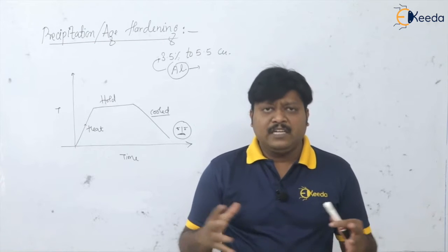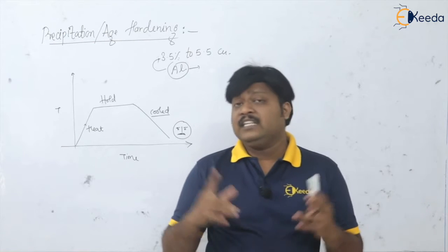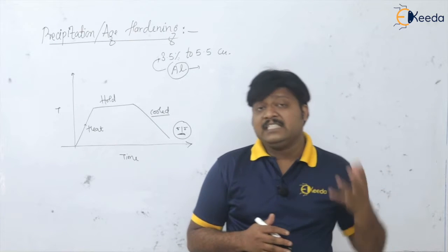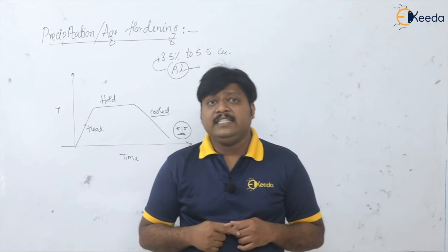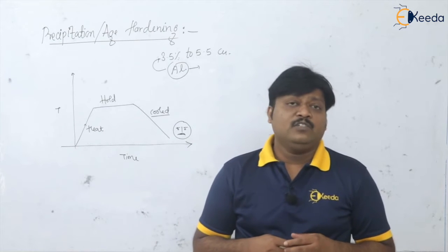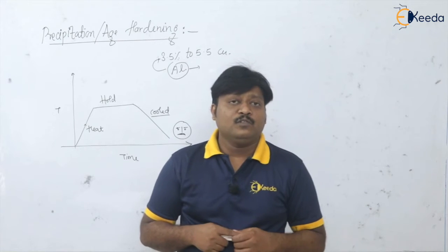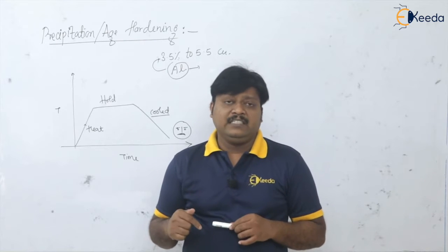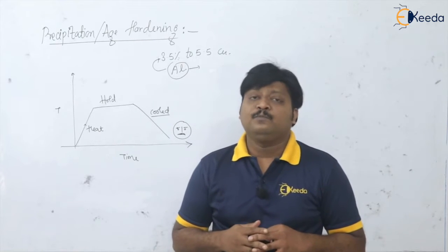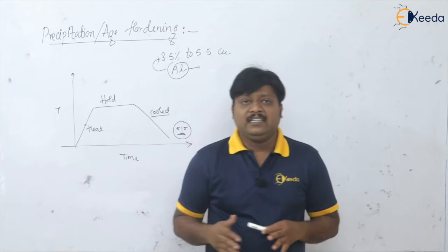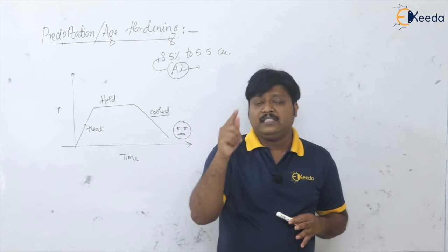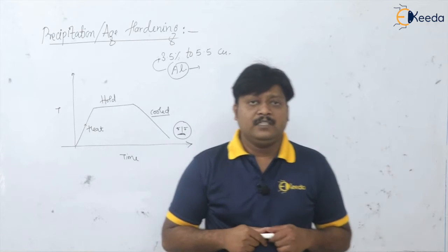He knew how to use all these variables. One thing is clear: if you want martensite, you have to heat above the austenitic temperature range, and it is necessary to quench at such a rate that the cooling curve definitely bypasses the nose of the TTT curve, isn't it?